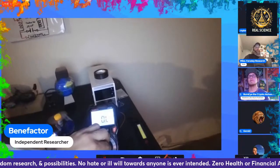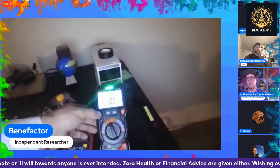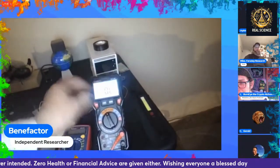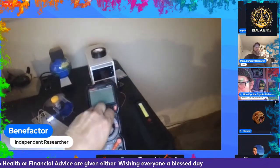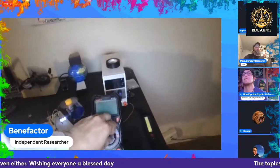That's doing something real crazy. Look at that. I put it on the ohm setting. You could have an intermittent short, or I don't know, is your device on? If your device is on, shut it off. Just do it with the meter. Yeah, shut your coil off.